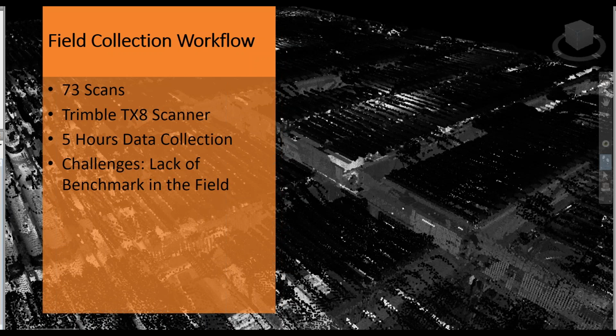And one of the major challenges, and something we can talk about later, is just setting the benchmark. It is critical for Verity to be able to do its work to set proper benchmarks in the field. And we had an XY axis, but the Z axis was not obtainable on the day I was there, and it was a bit frustrating to actually run the software and find out that we were 2 inches in the wrong direction and then rerun the software. But Verity is good for that. We were able to actually analyze where the point cloud should have been based on the data that was presented in front of us.